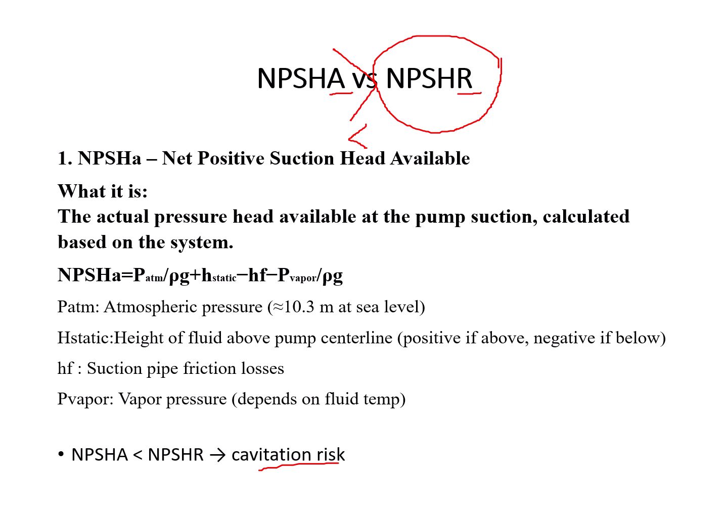This depends on the impeller design, or you can reduce pump speed if it is a variable speed pump. Reducing the pump speed, the RPM, will also ensure a low required net positive suction head, which will prevent cavitation.